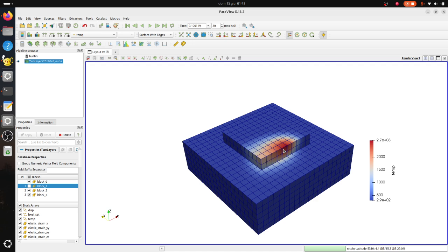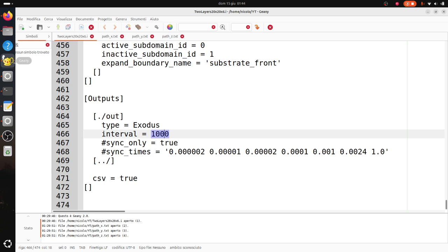When you set the time step for the simulation, you cannot set it too big. You need to make sure there is a good interpolation in time, so it takes many time steps for the heat source to cross a single element. In this case, we went for very accurate results, so we set probably around 100, and then the solver was cutting the time step if it wasn't converging. But this is the type of requirement, which is why direct thermomechanical simulations are very computationally intensive.